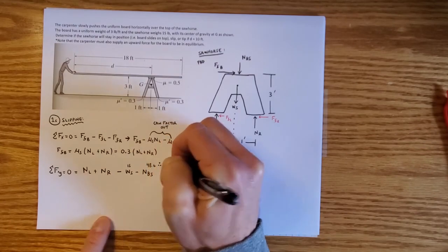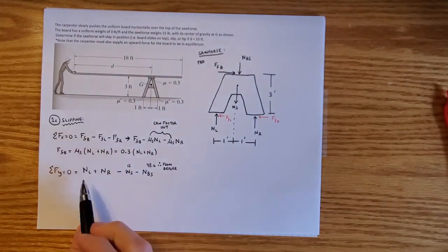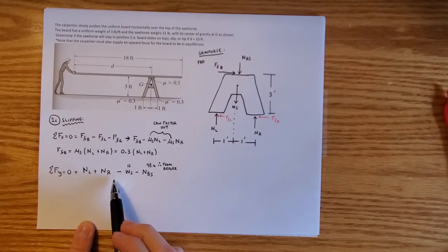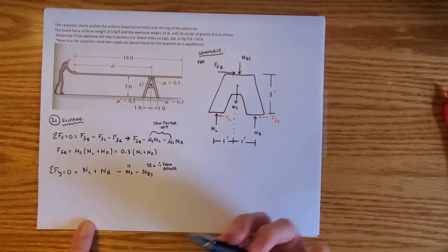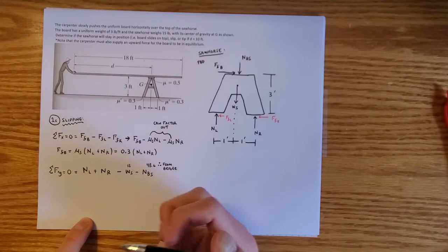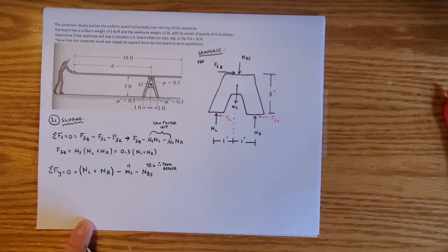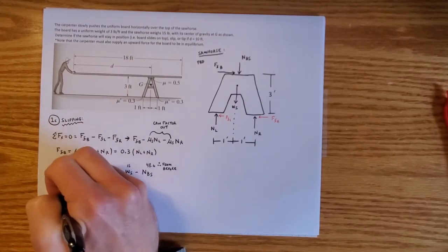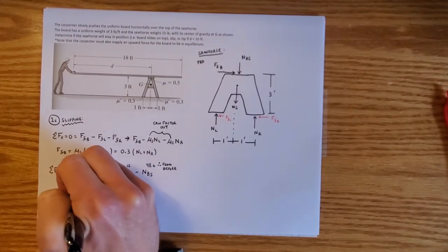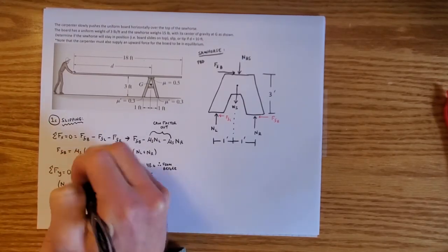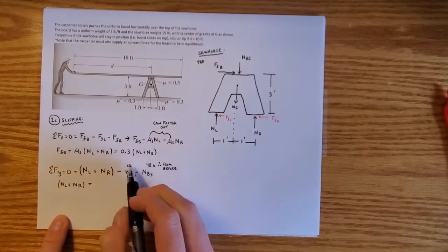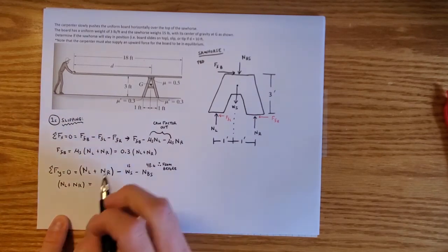Now the reason why I factor this out up here is because, as you can see in our sum of the forces in the y equation, we would have technically had two unknowns. So I would have had to do a moment equation or something like that, which would have gotten a little bit tricky. But conveniently, I can now bundle these two variables right here as a single variable. And what I get is that NL plus NR as a unit is equal to 15 plus 48.6,